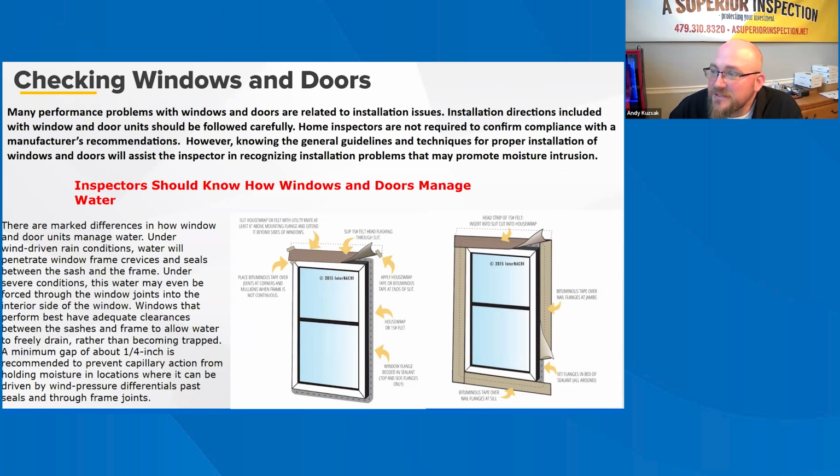Frames that rely on seals and sealants at internal and exposed joints will eventually leak water as these joints fail over time. The life expectancy of a window and door unit may vary widely from 10 to 50 years, depending on unit type and materials, exposure, maintenance, types of seals, sealants used at joints, and other factors. Frames that rely on welding of the joints rather than sealants will generally provide a longer moisture-resistant service life.